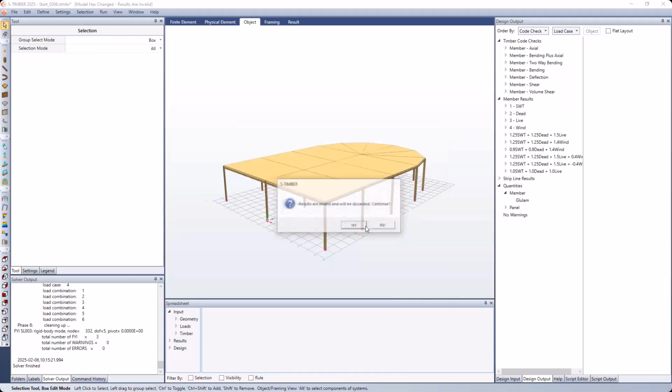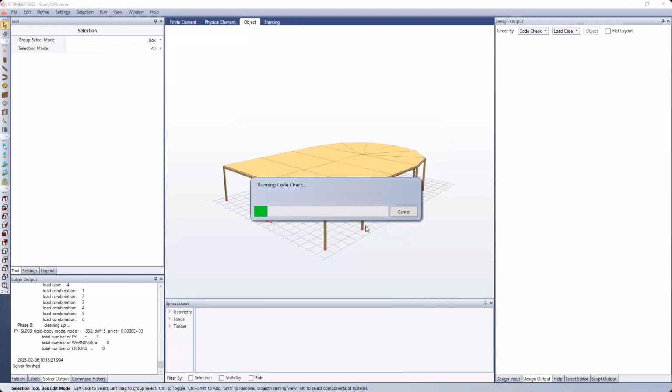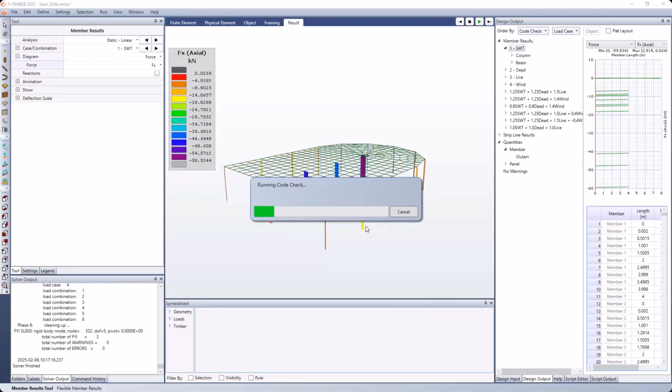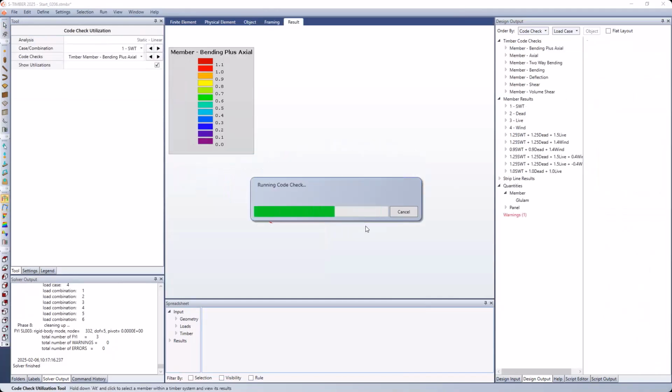And it's possible if we have a large change in our cross-sectional size that those demands that drove the design of our sections originally might not necessarily have been an accurate representation of the forces that would exist in a real model once we resize those sections. So we might get some failing utilization still, and we can certainly address those.